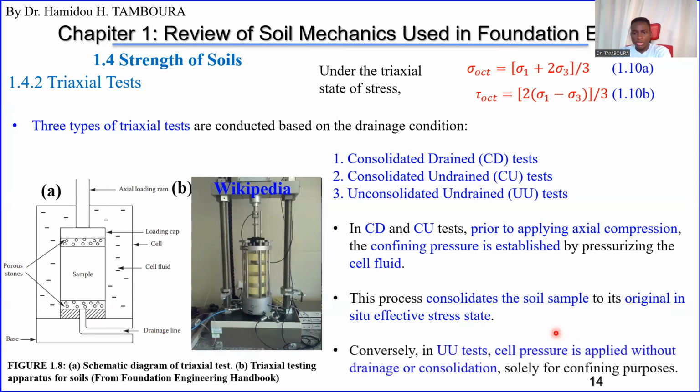So if you check now this case, unconsolidated and undrained, as the name says, unconsolidated, it did not consolidate. Okay. So the cell pressure is applied without drainage or without consolidation. That is the difference between this one and these two. Not drained and not consolidated.